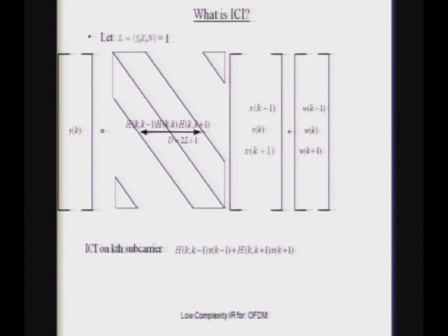And this is kind of like ISI in single carrier systems. You have the inter-symbol interference. This is an equivalent of that in the frequency domain. But in this case, you only have adjacent subcarriers interfering. You don't have enough spread where you could have collisions between two or three off to the side. No, because that is the beauty of this. This is a sparse matrix. So along here you can neglect them.